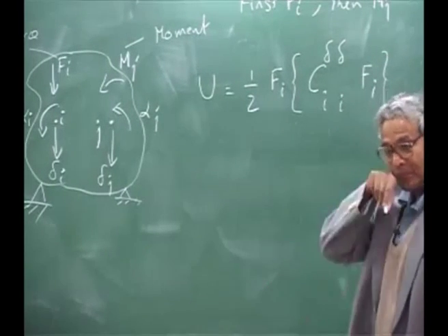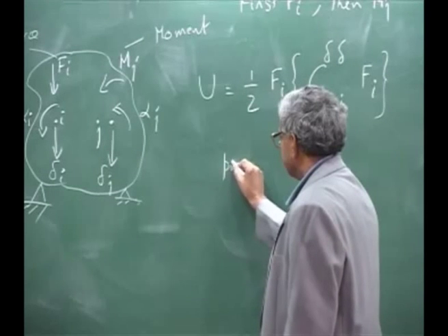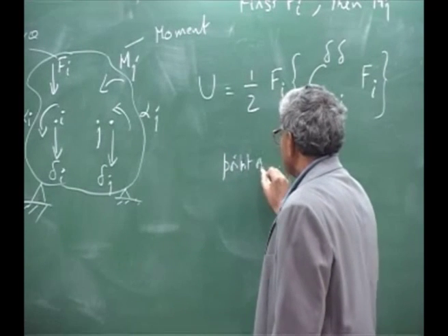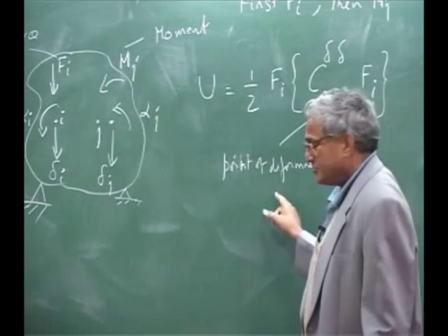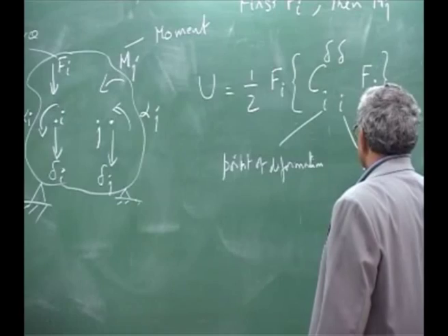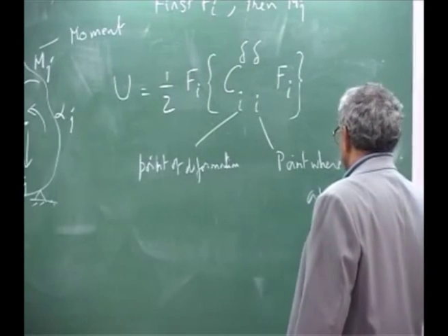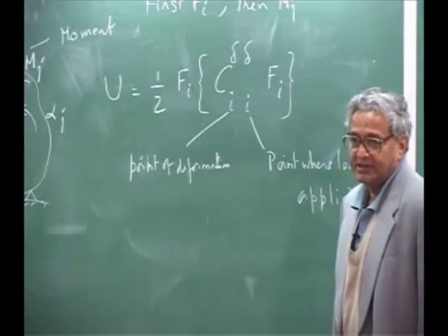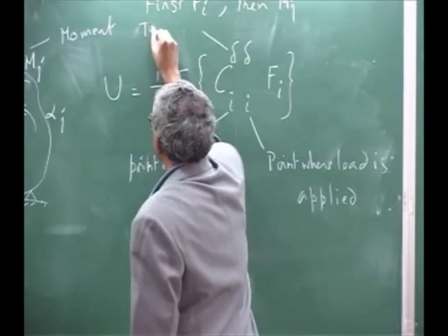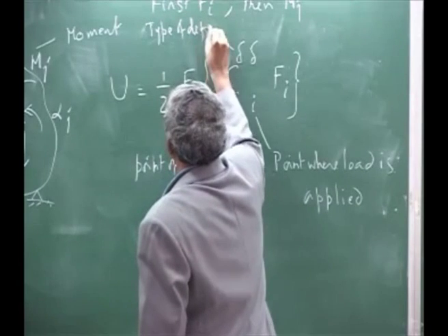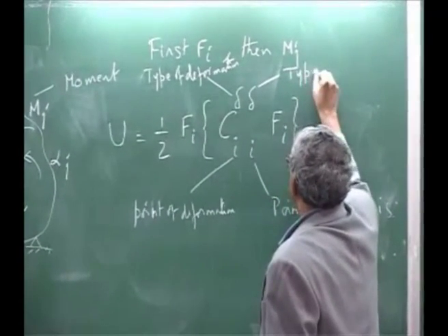Please note the notation: this is the point at which you are measuring the deformation, this is the point where the load is applied, this is the type of deformation, and this is the type of load.